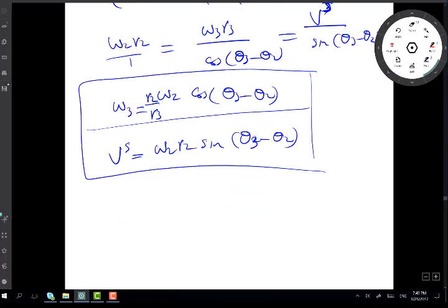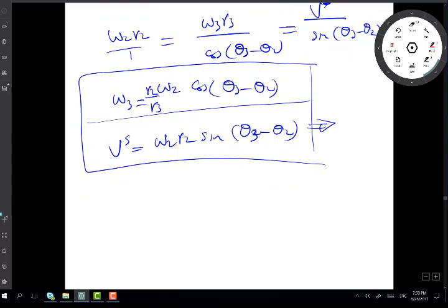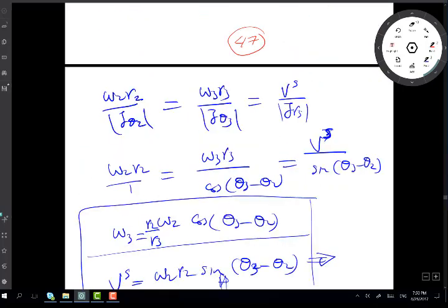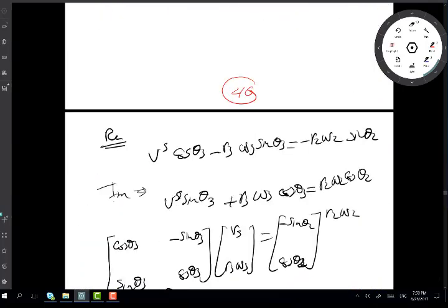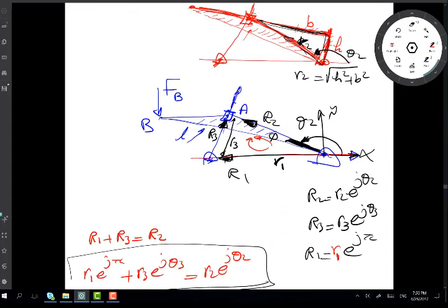Now, you need to be able to control the rate at which the hydraulic cylinder extends to match this equation, right? So you can plot this against theta 2, Vs, whatever you find. This will give you what you need to apply at the hydraulic cylinder end to be able to drive the linkage in the fashion that you wanted.